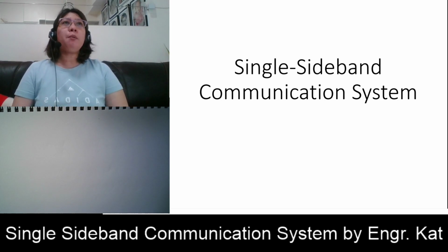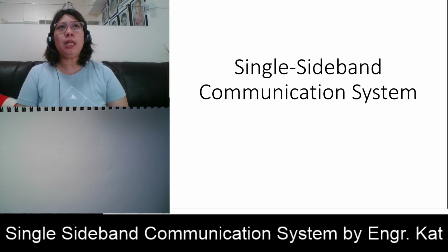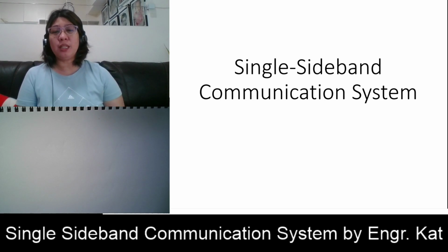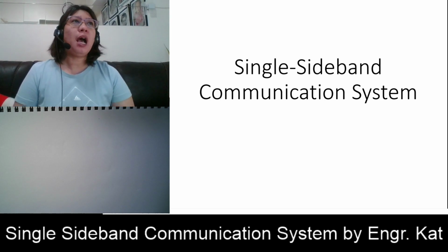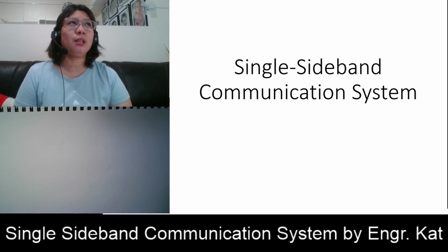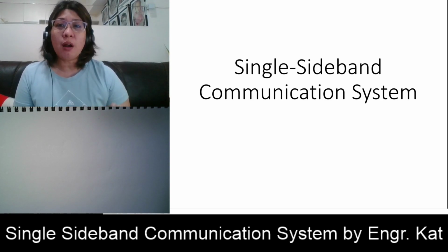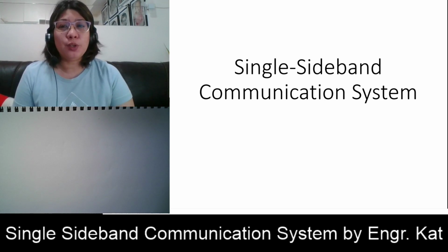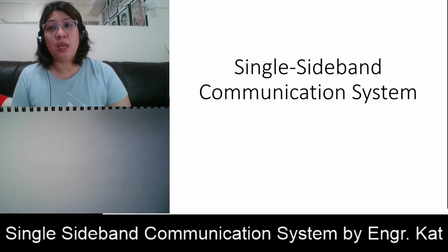Our conventional AM has two major disadvantages. Usually the carrier power constitutes two-thirds or more of the total transmitted power. So the majority of the transmitted power is allocated for the carrier signal. However, as we also know, the carrier signal contains no information. So where is the information? The information is located in the sidebands. Therefore, the power provided in the carrier is simply being wasted.